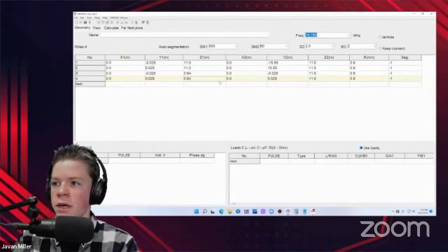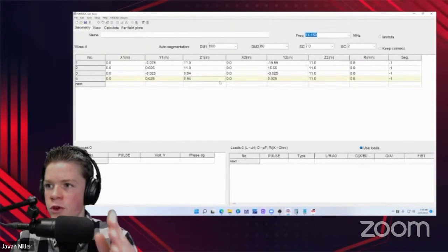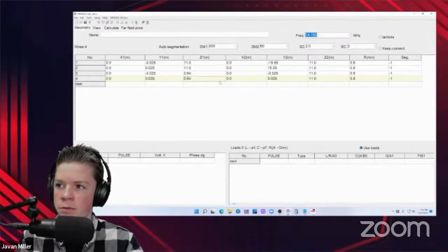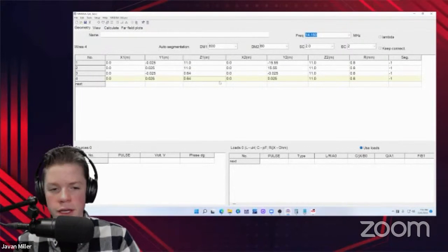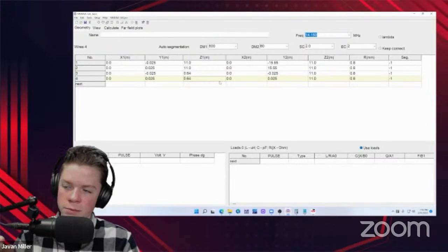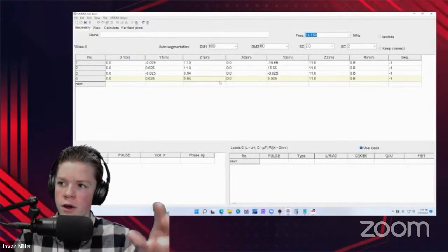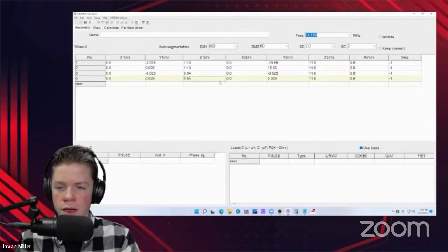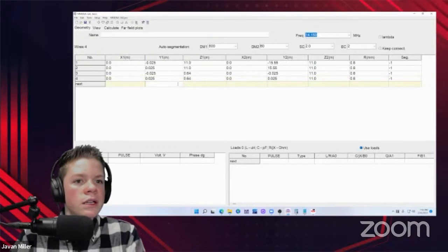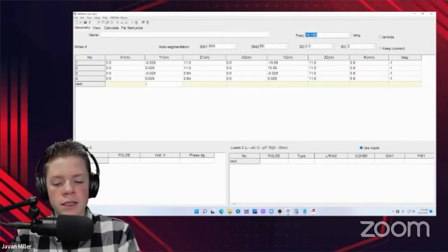And then I'm going to be doing a bridging wire in between the two parallel wires for the parallel feed line, and then just do a load in the center of that. So there's really no good way to bridge a feed point across two parallel wires like that, except for doing a wire across the bottom. So that's what I'll do here. So let's see.